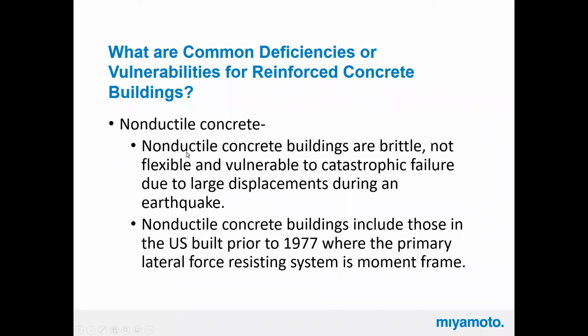Non-ductile concretes are brittle, they aren't ductile, they don't have a lot of post-yield capacity, and they don't have the ability to dissipate energy over a longer shaking event. So that's why they're of massive concern. And with brittle failures comes rapid collapse. So that's one of the things we're very attentive to as we do our engineering work.